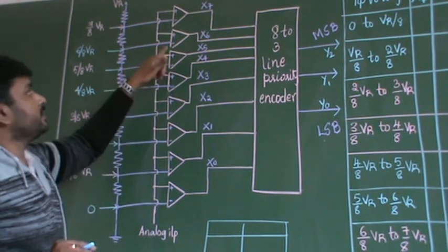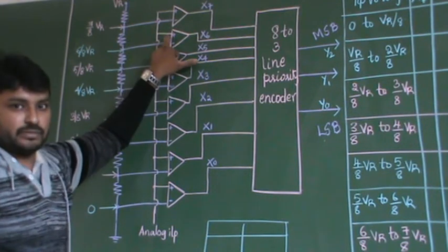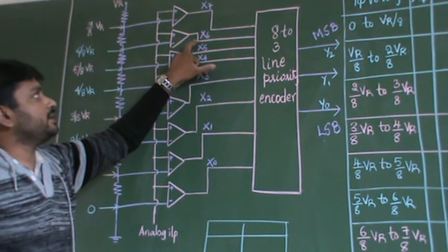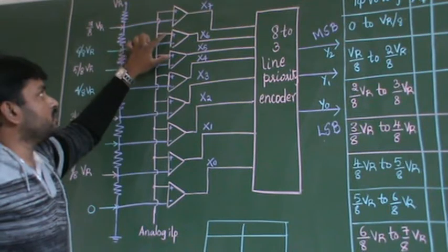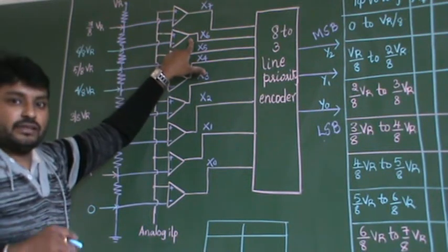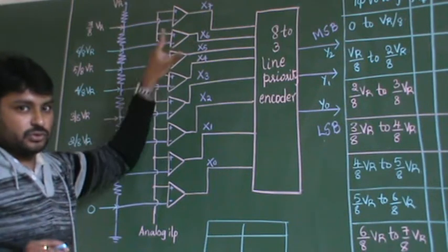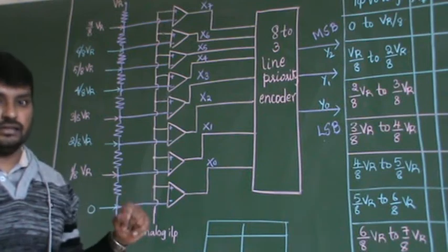In the same way, if the negative terminal has a higher quantity than the positive terminal, then I call the output 0. One more case: if both quantities are equal, then your output will keep the same previous value. I have already explained this with a small table, and I will explain it later on.